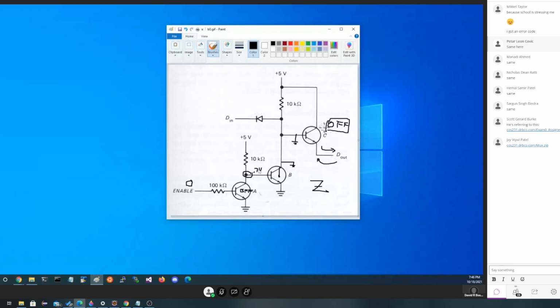Now you might say, well, what good is the thing? Why would we even want one of these things? They sound much too hard. Well, the reason is that most of the circuits we've designed, remember our AND gate that we have? We can't take that output and take another gate, maybe an OR gate over here, and tie their outputs together and then look at them, because if one is doing a 0 and the other is doing a 1, something's going to catch on fire.